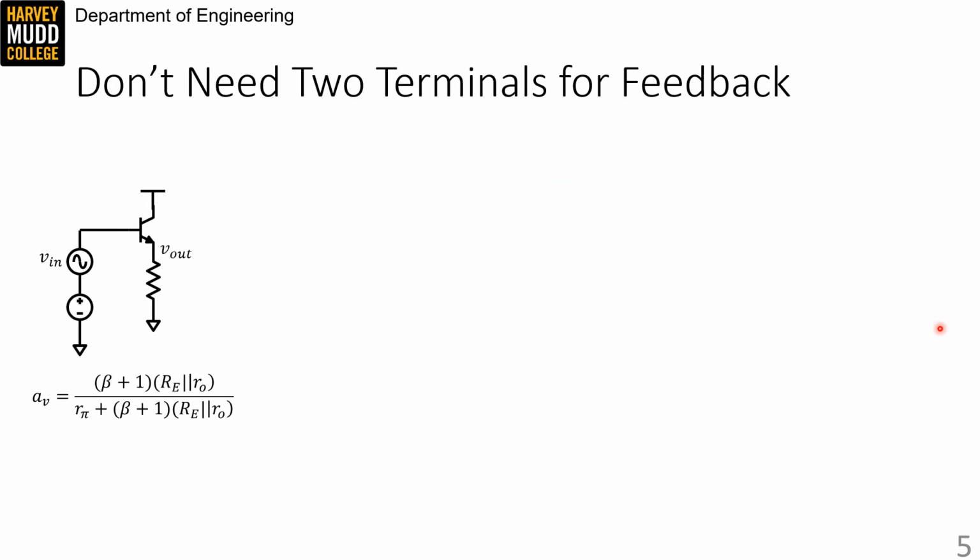We're going to be looking at feedback for lots of op-amp systems, and those systems always have 2 terminals. However, you don't need 2 terminals on a circuit to include feedback in it, and we can see that by observing that feedback is actually baked into the operation of an emitter-follower. I included this slide for 2 reasons. First, to show that one-terminal circuits can have feedback in surprising places, and second, to show that the emitter-follower is really easy to model using feedback analysis, which I find elegant.